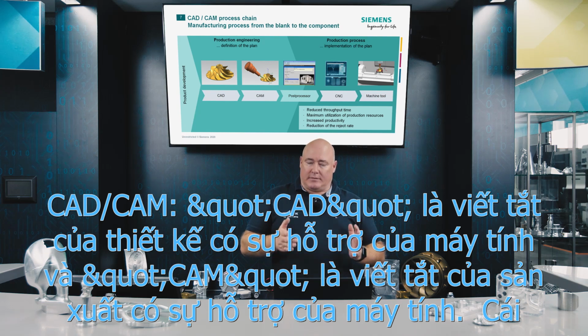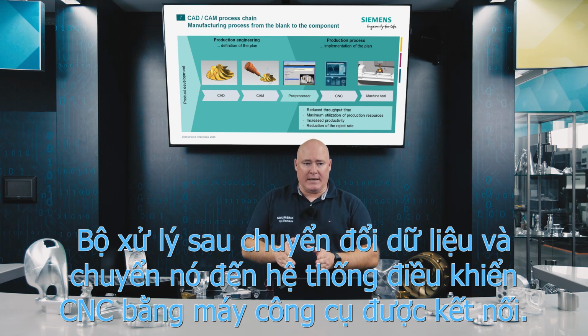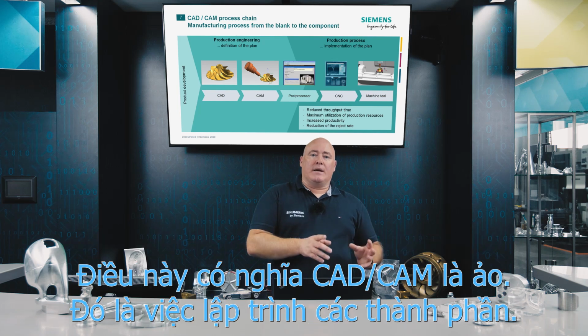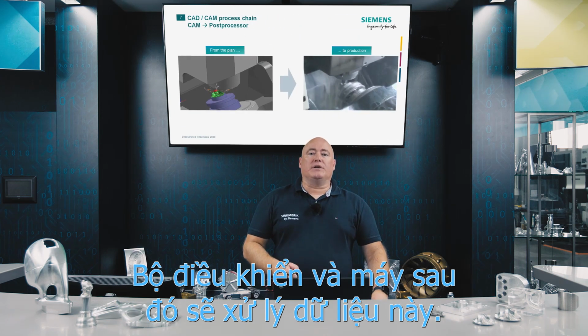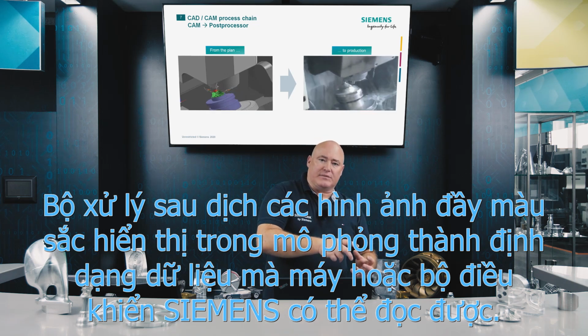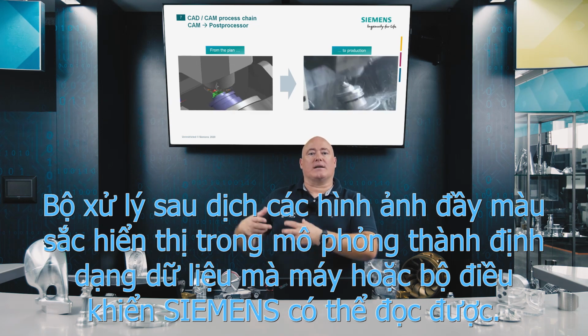CAD stands for Computer Aided Design and CAM stands for Computer Aided Manufacturing. The so-called post-processor is connected to this. The post-processor converts the data and transfers it to the CNC control system with the connected machine tool. This means CAD/CAM is virtual. It's the programming of the component. The control and the machine then process this data. The post-processor translates the colorful images shown in the simulation into a data format that the machine or the Siemens control can read.